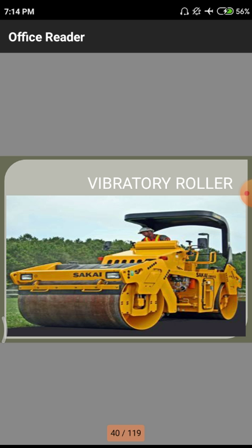That means waste coming from the petroleum industry, that is tar or bitumen. Those are used to bind the particles, that means the waste chips, so that due to these vibratory rollers all those come together and densify as a particular layer on the surface of the road level.